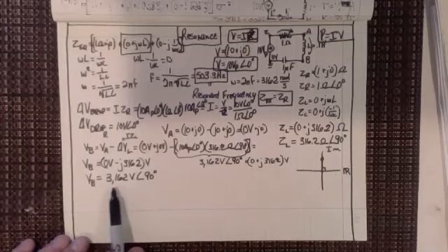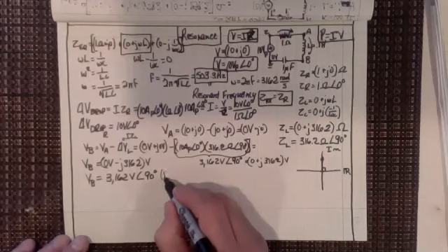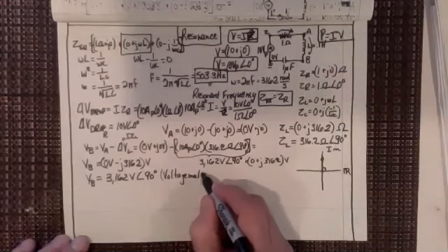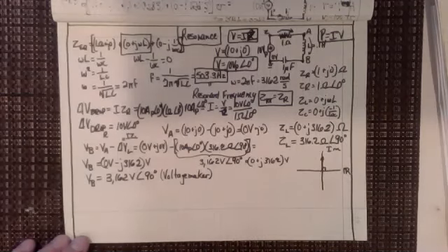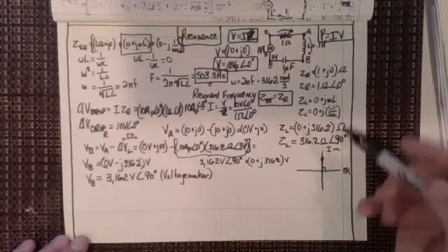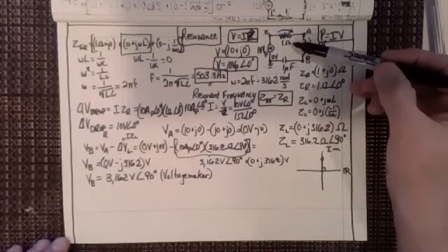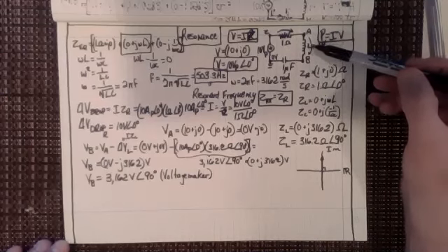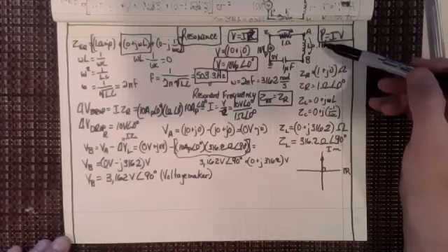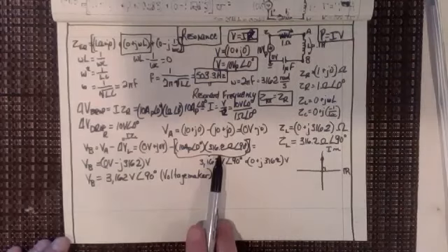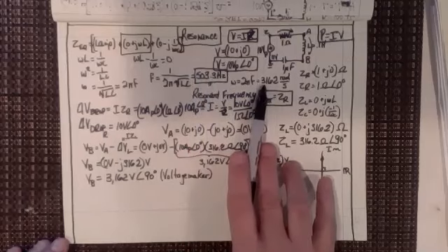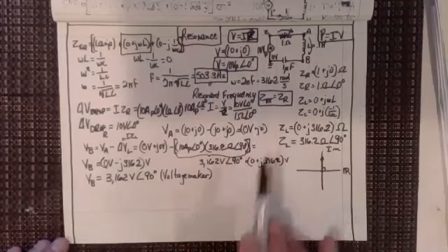Now, that's my voltage, and I call this the voltage maker circuit, right? And what do you want to do when you're making this voltage maker circuit? Well, you want to get the current as high as possible. And of course, I did that by reducing the resistance to as low a value as I can. And then you also want to get this over here. Now you can see that if I'm using a 0.1 Henry inductor, that brings it up to this, right? Because I'm still using it at the 503 hertz or 3162 radians per second.